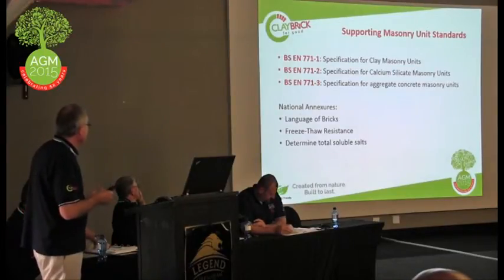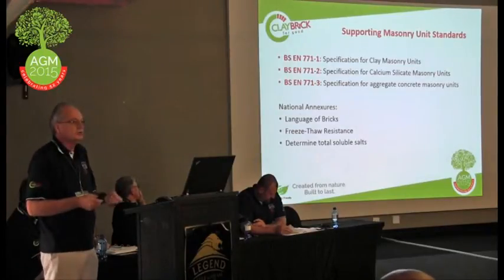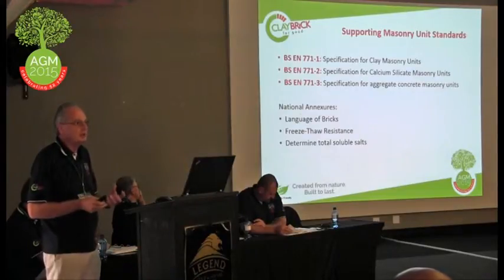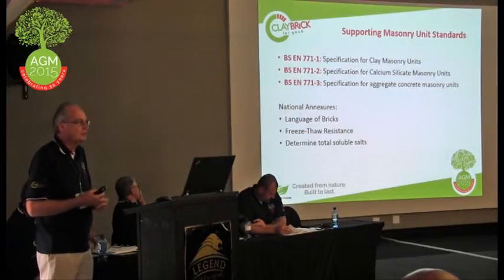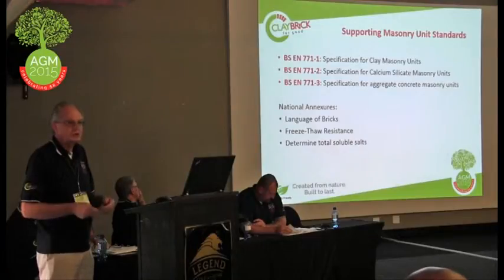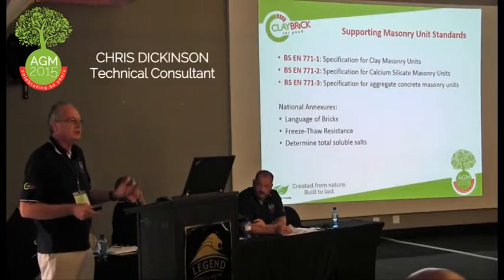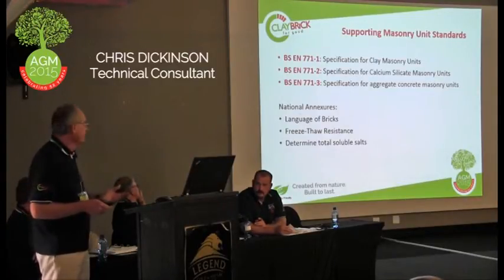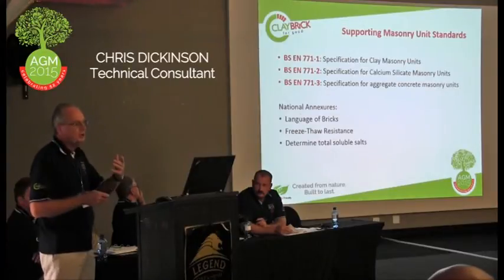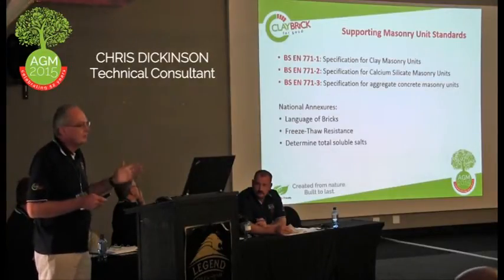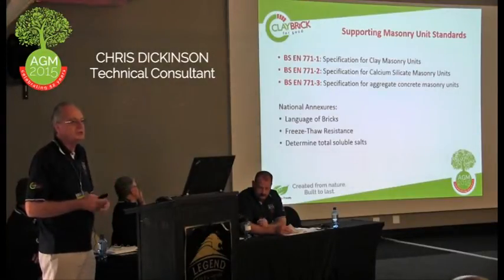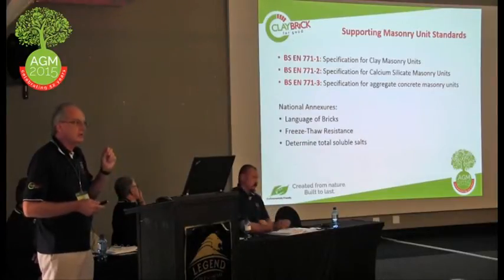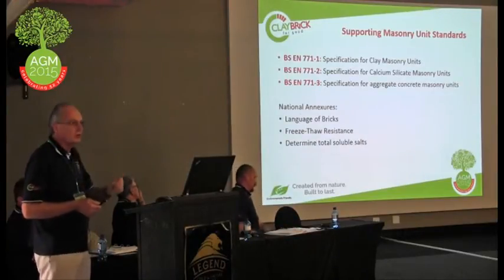Then, again, in the European standards, total soluble salts is required to be measured on fired product. Again, this is quite a complex test procedure, and it's expensive and doesn't actually tell us anything, because what it's trying to do is say, is your product durable under the various climatic conditions? Now, that again, we would say is not applicable to South Africa, and we would either have to develop a durability test or the manufacturer themselves indicate what is required.